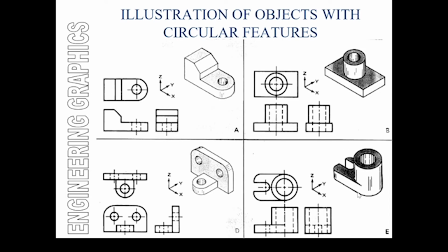This one is a very peculiar one indeed, because there is a tangential relationship between this cylinder here and this bit of detail here, so it wraps around quite nicely in a smooth manner, and that actually results in a lack of edge here. So when we look at this, without seeing that, it can be quite confusing. However, there are a couple of other views here which give us information about what might be going on in that region, and looking at that, I know that wraps around that, hence there is no edge.